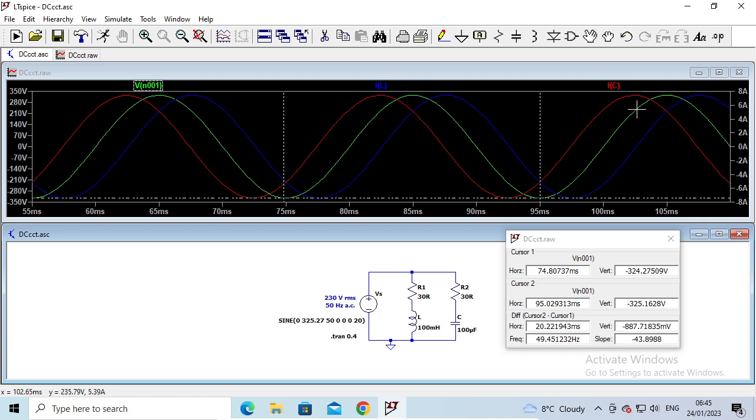And you can measure that in the form of radians. So there are 2 pi radians in one complete cycle of the waveform. But if there's some fraction of one cycle that a waveform lags behind our reference waveform here, we can express that in radians, or similarly, if it's ahead of it, we can express that in radians. And we're going to see that in our phasor calculation. So I'll leave this sitting here and I'm going to go and do this calculation using phasors in Octave. So let's switch over to Octave now.